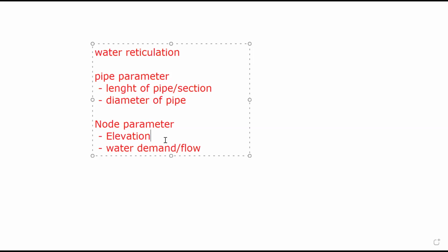Are we together? That's why when the surveyor goes to site, what does the surveyor do? The surveyor goes to do two things. The first thing is to measure the elevation, to know the height, to know the undulation of the land. And with the undulation of the land, you can now determine the length of each section. What is the distance between Airport Road and Gwagwalada? That length is what you need to calculate your losses using the frictional factor of the pipe material.